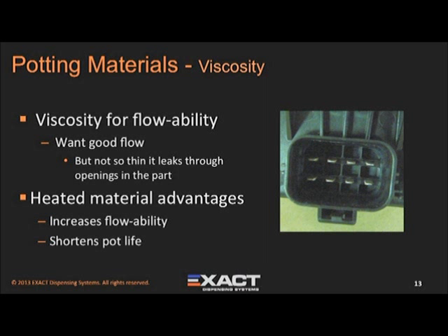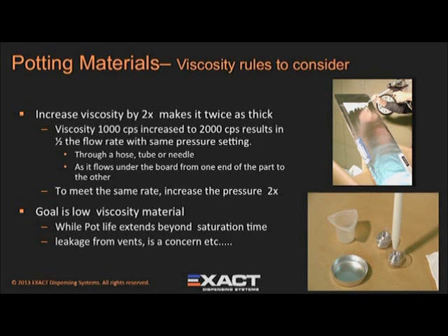One way to increase flowability is by adding heat. Heat reduces viscosity and can improve consistency of viscosity, but it also reduces pot life. Reduced pot life can be good, more and faster production, or bad: material cures before you get it into its correct place on your part. There are a few viscosity rules for you to have in mind when this subject is discussed.